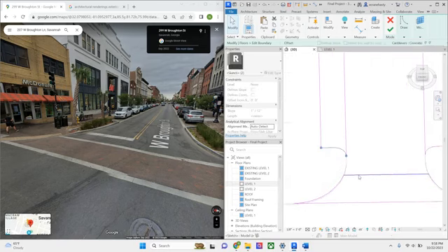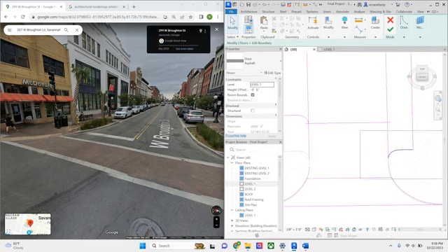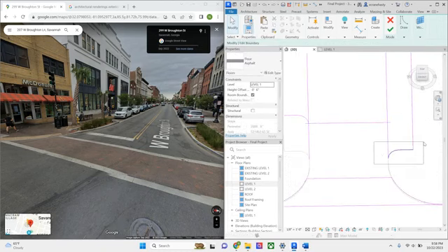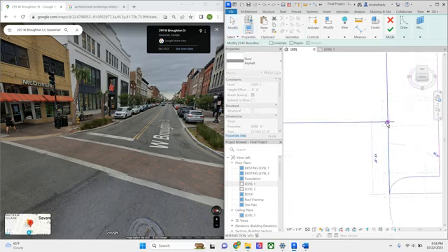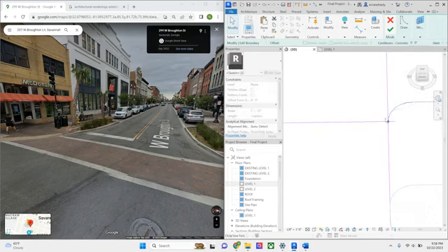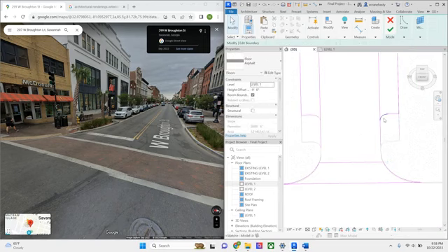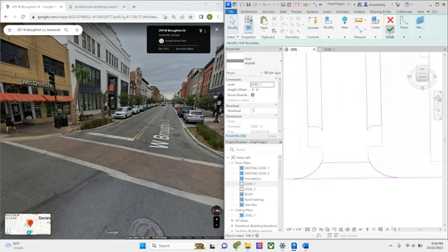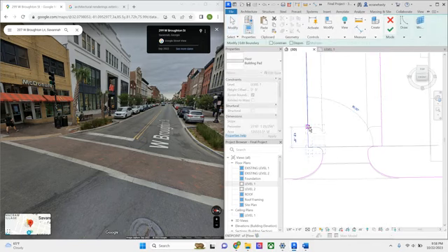So remember, click, drag to the left only selects the things that are in the box. Click, drag to the right selects everything that I touch. So I use this a lot. MV to move, and I'm just going to move it to where it attaches. It shows me where I am. It'll highlight the two lines and then the X shows us where they intersect. So it's just telling me where that 20-foot is located off of this crosswalk. And then I might move this as well.